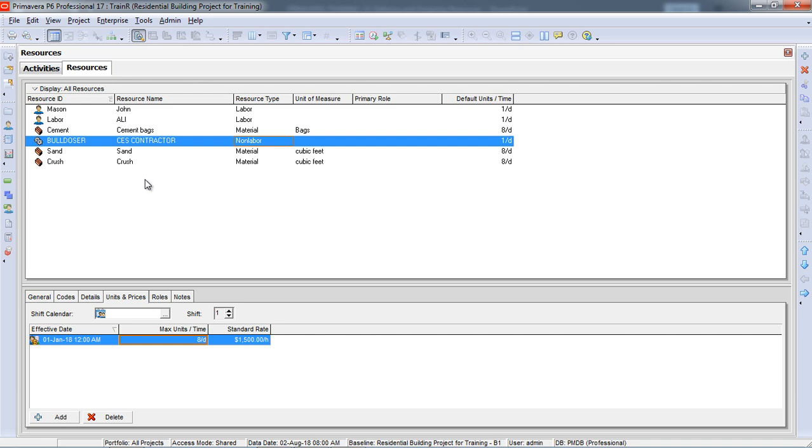So basically these resources come from the rate analysis of the activities. For example, a brickwork activity of 20 feet height wall and 30 feet long wall of 9 inch, then how much brickwork is required. So you can also define bricks, sand, cement, so these materials, and also labor and masons are required. So all these resources you can define here and put into the activities.